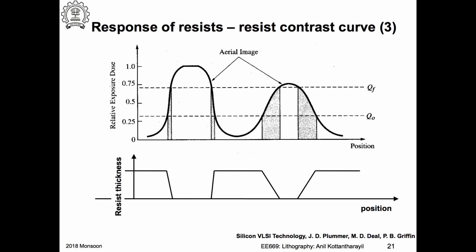They get implanted, but in this region, they would get implanted into the photoresist, not into this. But then this part, for example, the ions have certain energy, so that the implanted ion concentration comes to nearly zero or negligible within this depth.